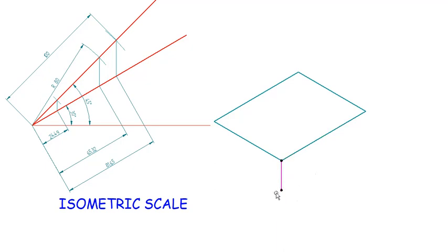That means 3 boxes, which we use to get it in the iso scale. So from here again I will just draw the line. Again I'll take the distance and cut an arc, here also and here also. Next I'm going to join it. So this is a rectangular slab.